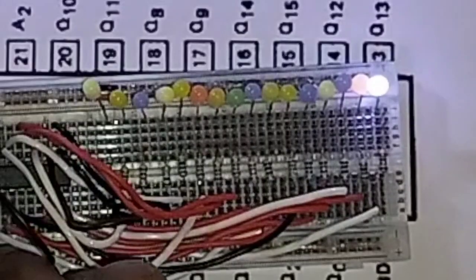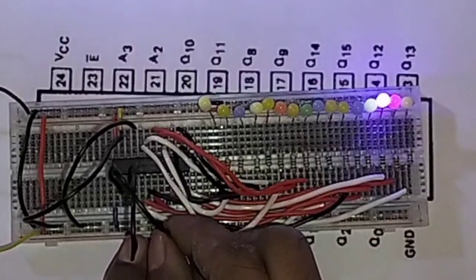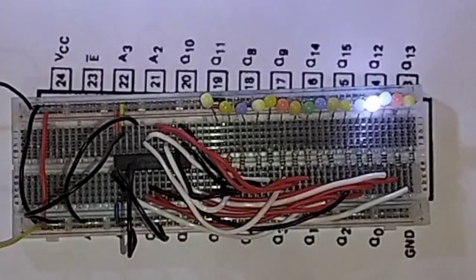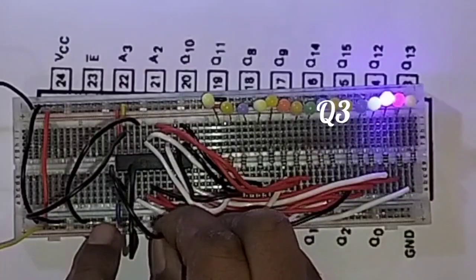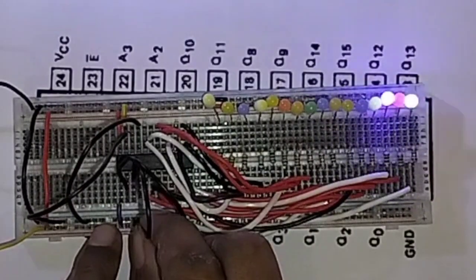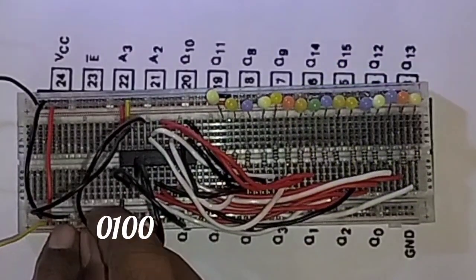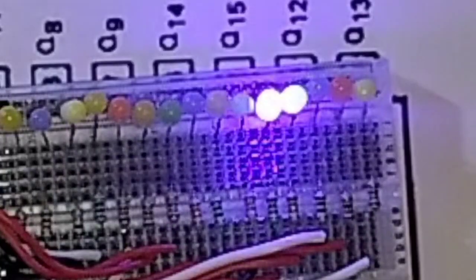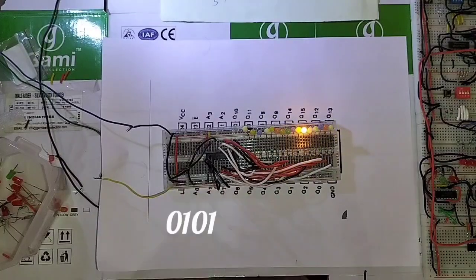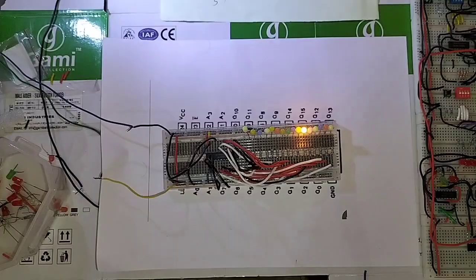The 4-bit computer has a 2-bit instruction register. So the most significant bits, that is A2 and A3, are connected to the instruction register. The output lines, that is Q0 to Q15, are connected to our micro instructions. I will explain that whole thing in the next video. The least significant bits, that is A0 and A1, are connected to the step counter. In our case, that is 7476.